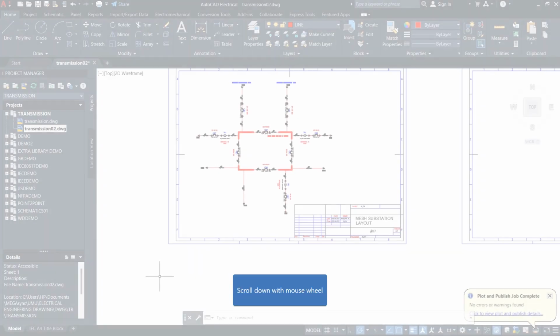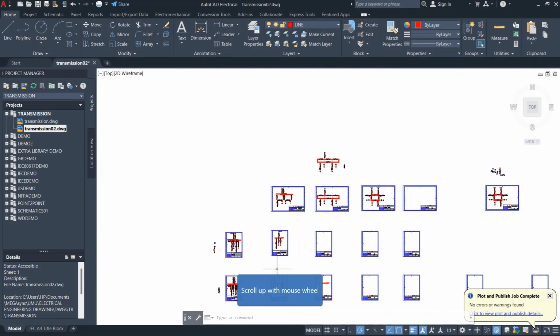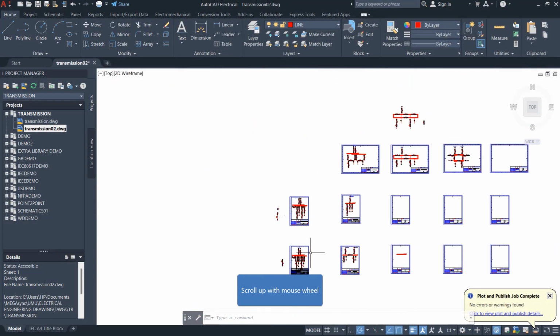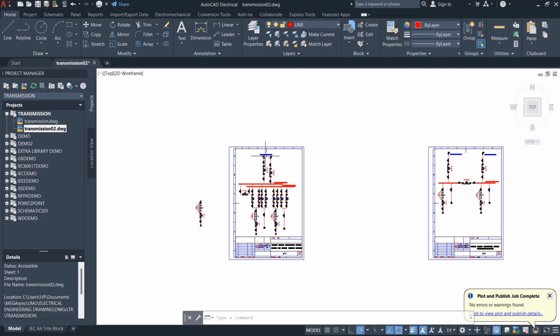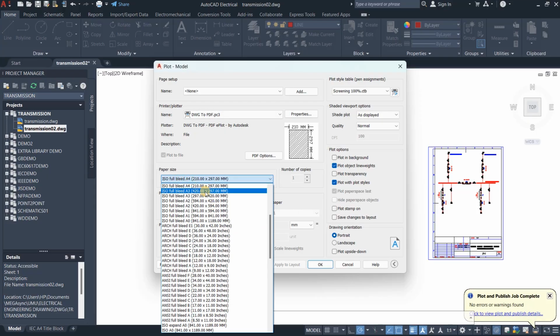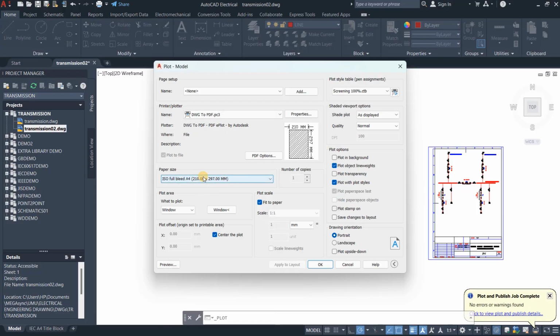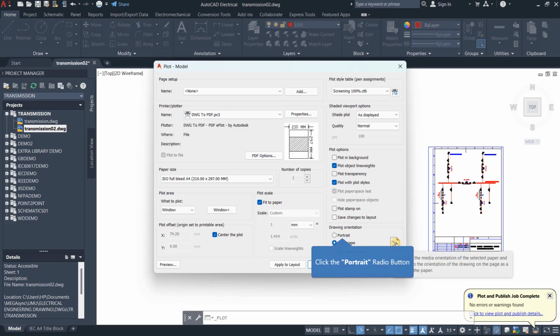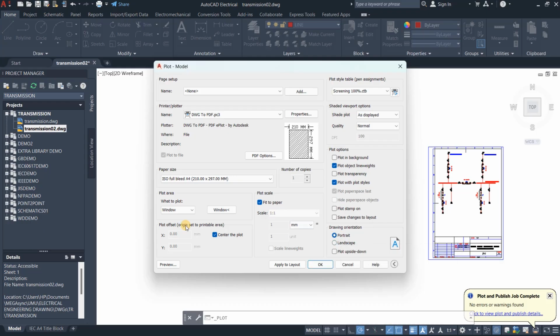Yeah. Right, so now let's try the A4. So for the A4, it doesn't matter what I choose, maybe this. So just again go ahead and click print, DWG to PDF as usual. Then it's already selected for us, ISO A4. Make sure you choose that one in this orientation, which is the same as that of your template. And you are printing in portrait, so make sure it's still portrait. Otherwise, if you click landscape, then the drawing flips on its side. So you want the drawing to be upright.